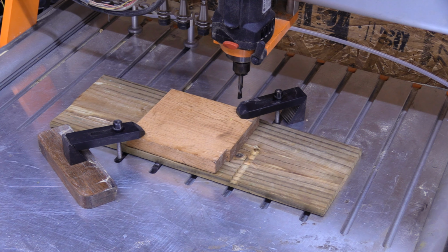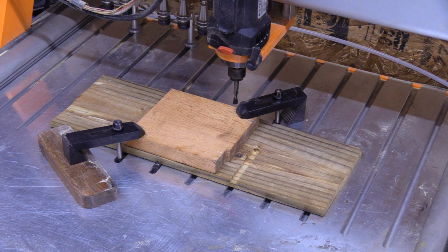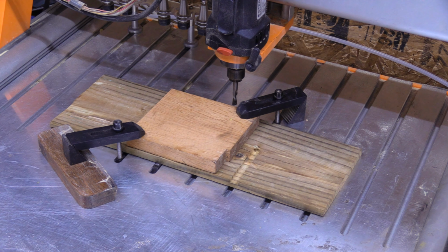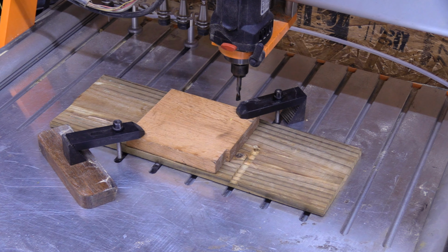So let's go up to Z, there's Z6. And if I come down here, there's your Y0. All right, so I'll need to move my Y0 in order to make this work. But I'm going to send it a command right now to go to Y0, and the command I'm typing is that gcode, G1 space Y0. All right, now it's going to do it really slowly. G1 Y0 F300.